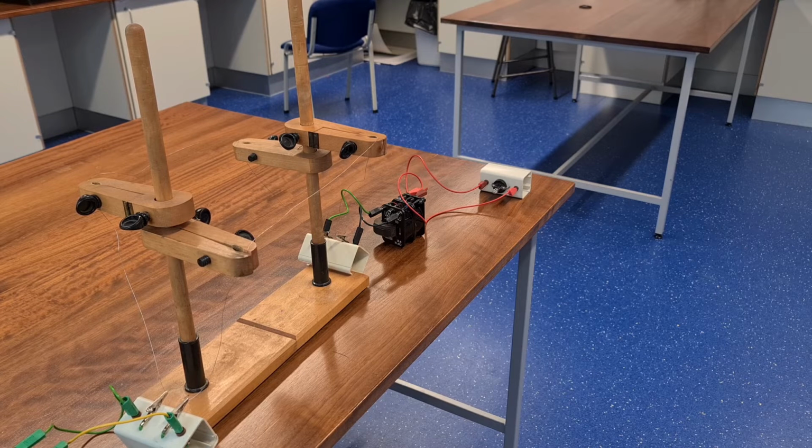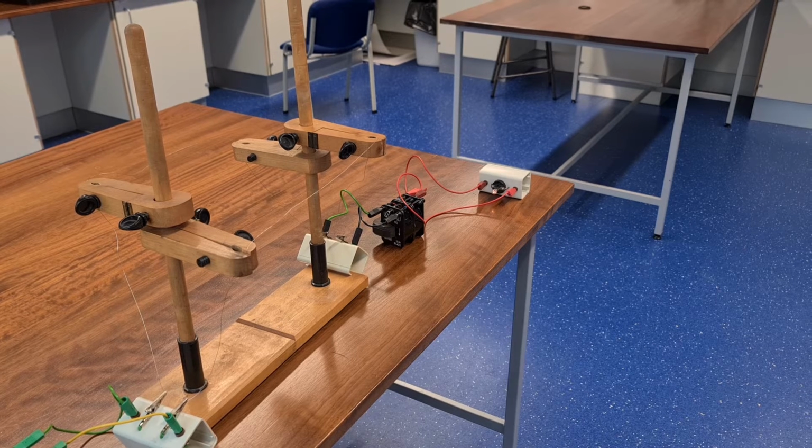But an interesting thing is if I turn this to direct current, which it is now, the light bulb has not illuminated because all of the wire between here and there has not been able to carry the energy without losing it as heat, and it was also not the right kind of current to go through the transformers. So though we will talk about this in more detail later, you need to be convinced that alternating current is necessary for the transportation of this electrical energy over large distances using these devices known as transformers.